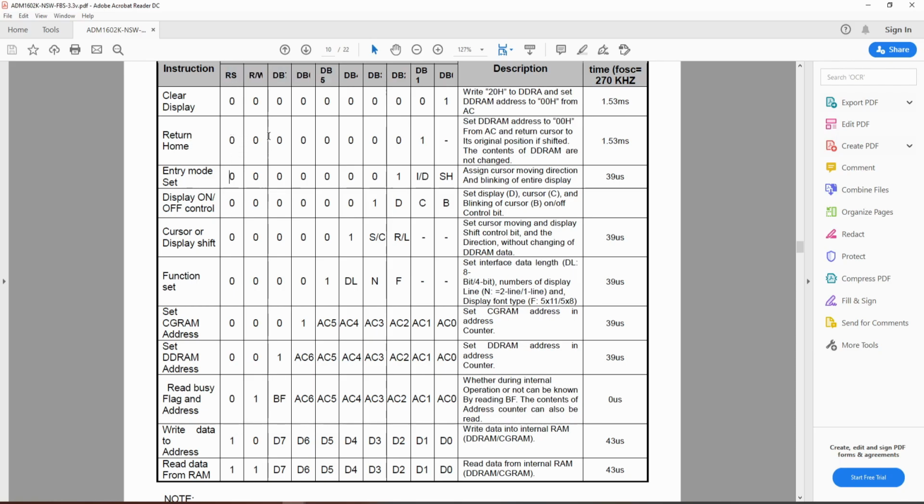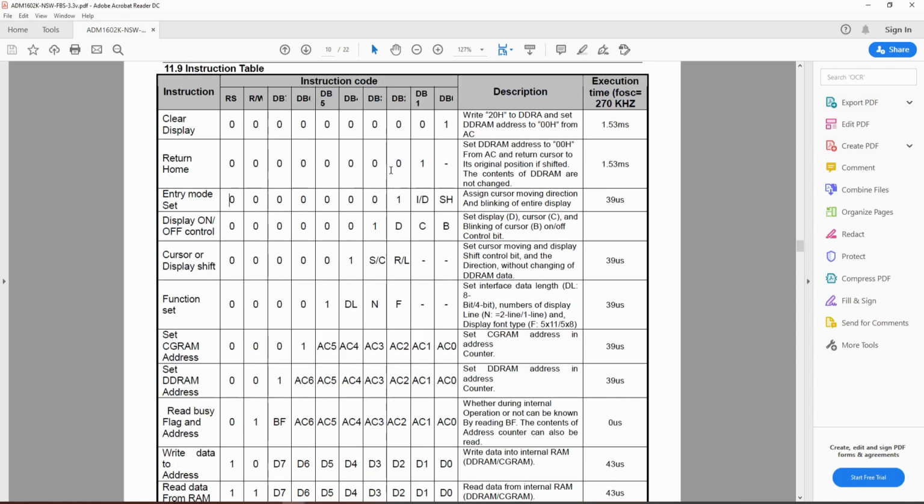So now to write on the instruction and set up the code, we are going to use mainly this first action, and not all of them, but a part of them. Okay, so let's take a look quickly at this one. So the first one, if we send to the instruction register all zeros, when I'm saying all zeros, it's about the data part, and we do have a 1, it comes back to the first place of writing.